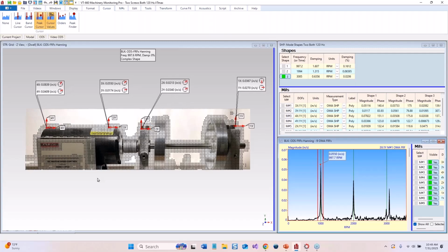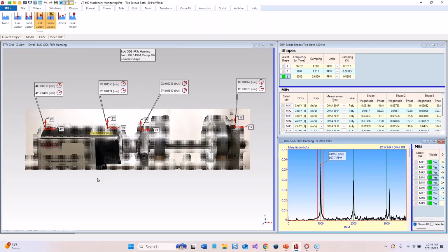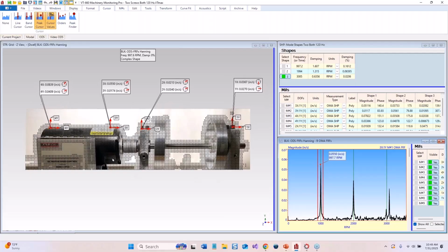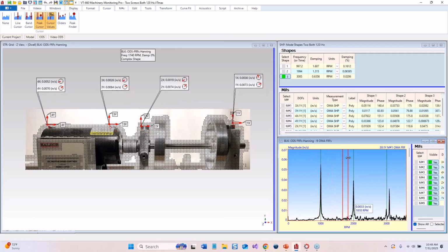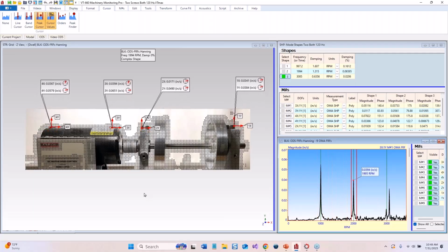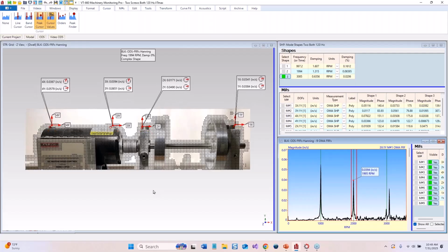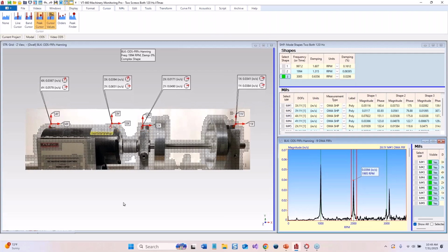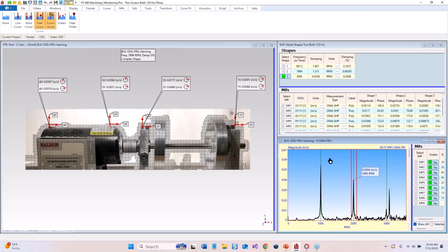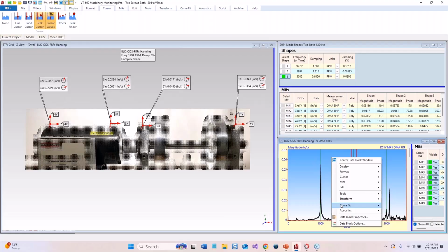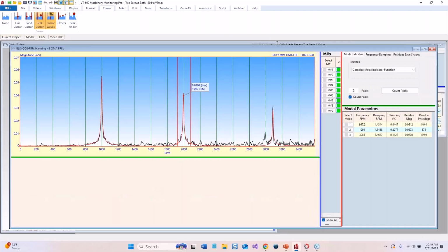it's pretty much in phase, with a little bit of difference. Typically, if you're looking for problems in a machine, you're going to look at these first 3 orders, maybe the first 5 orders. There's a lot of literature and a lot of knowledge from people in the machinery business who can say that a particular problem is unbalance, or a soft foot, or a coupling problem, or a gear problem, various mechanical issues that will affect the vibration. Let's do a real quick curve fit, and then we'll move on to facts.